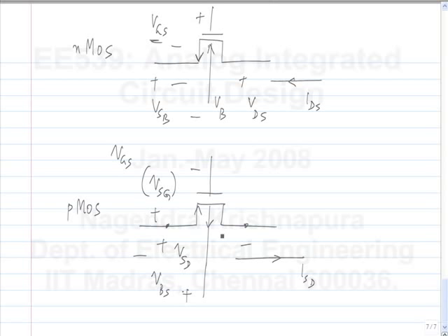of the notation. Now, if you are very uncomfortable with it, you can at least put, for the NMOS, mu Cox W by L, (VGS minus VT) squared. For the PMOS, the current direction is opposite and VGS and VT are both negative. So you can imagine something like this and assign the right direction for the current. So I won't talk about VSG, etc. It will always be VDS, VGS and VSB.